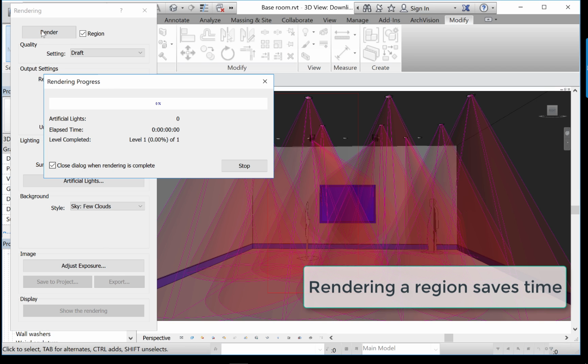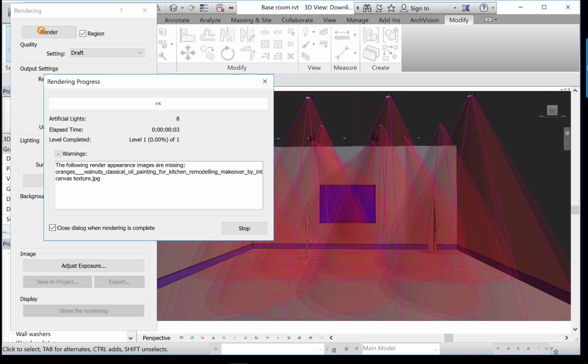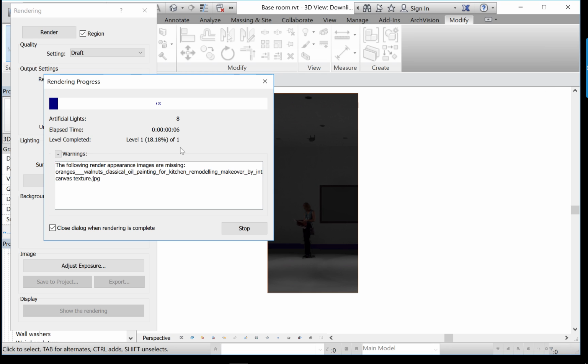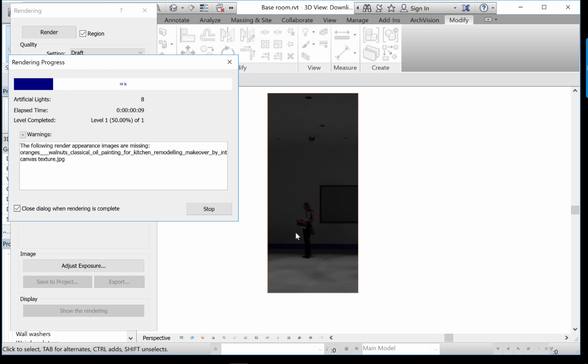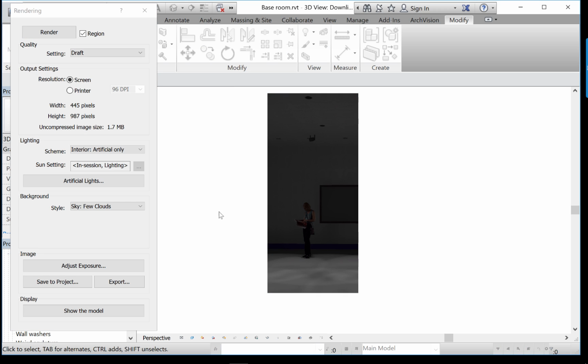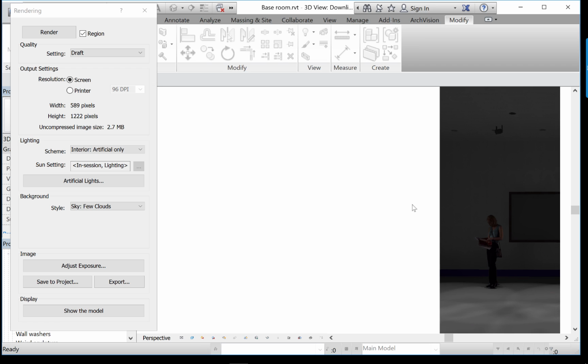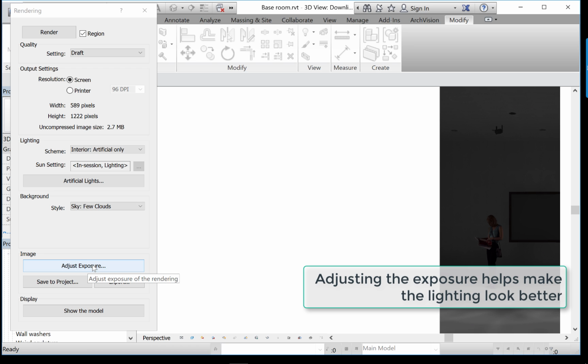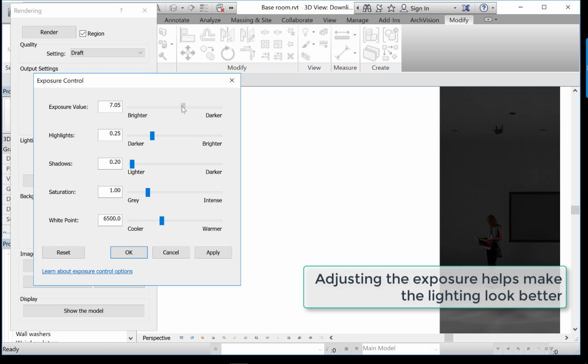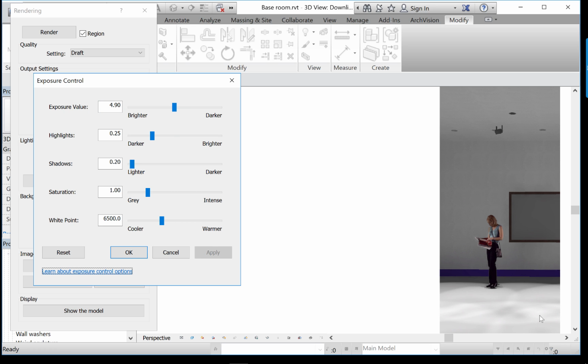Anyway, when you click render, what you'll see is that the computer is going to take some time to figure out how the rendering is going to look, but almost instantly you can see I'm getting a little preview. I'm going to stop the rendering, it's already done. I was going to stop it, but it's too quick for me. You can see that I'm already getting just a little bit of a preview of how my lighting is working. It's a little blotchy because of the low quality rendering setting. But I can come in here and I'll adjust this so that it's a little brighter. Okay. And I'm just basically trying to see, are the lights landing where I expect them to? And in fact, that's the pattern that I was expecting.